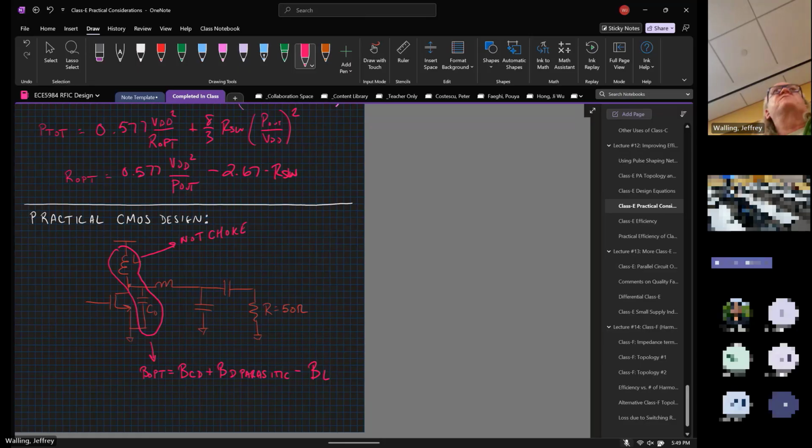Inductors have negative susceptance, right? Looking in this direction, the matching network is designed to transform 50 ohms to an impedance equal to R opt plus jX opt. So I can have my matching network make the impedance transformation to a real value, leaving some excess reactance that's going to be used to delay current. So it needs to be a positive reactance.